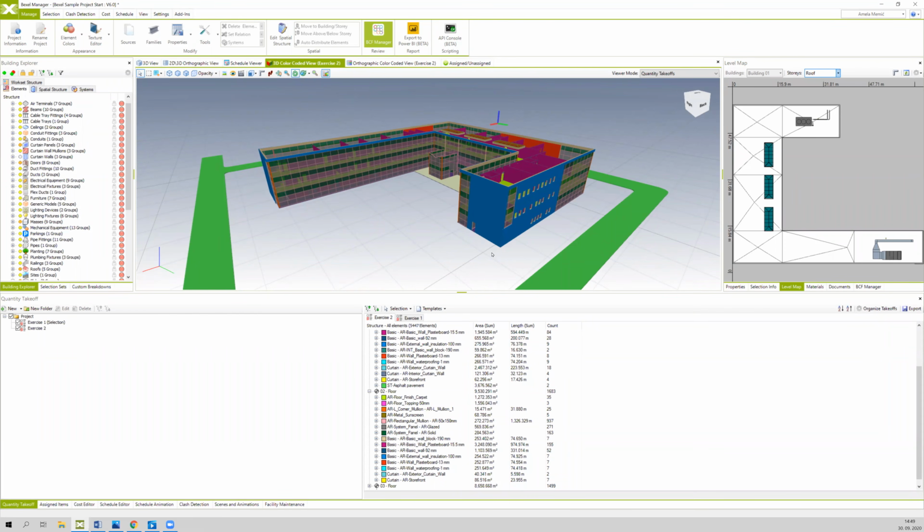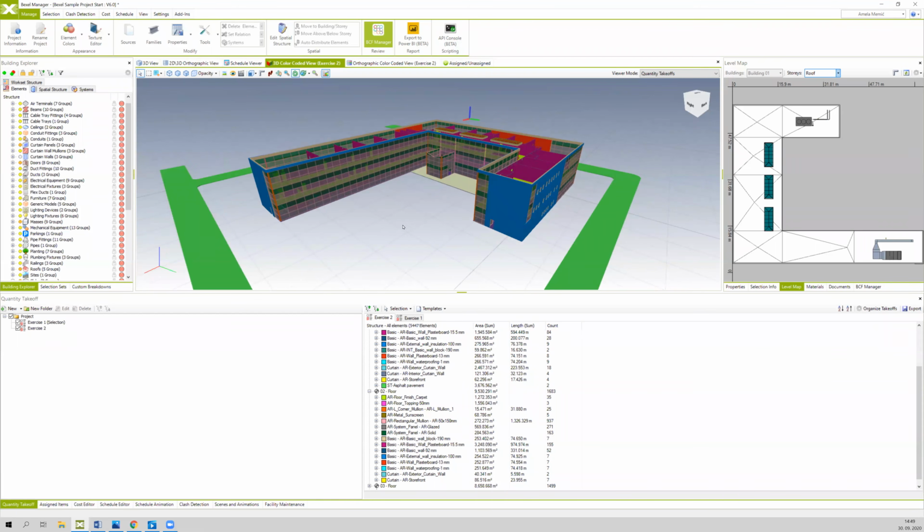So in the next exercise, we will use a discrete property, which is, as you all know, the master format property, because this property was used during various BIM analysis in previous lessons. And we will show you the process of how to create a quantity takeoff based on a master format property. So click again on the new command within the quantity takeoff and choose the option blank quantity takeoff.